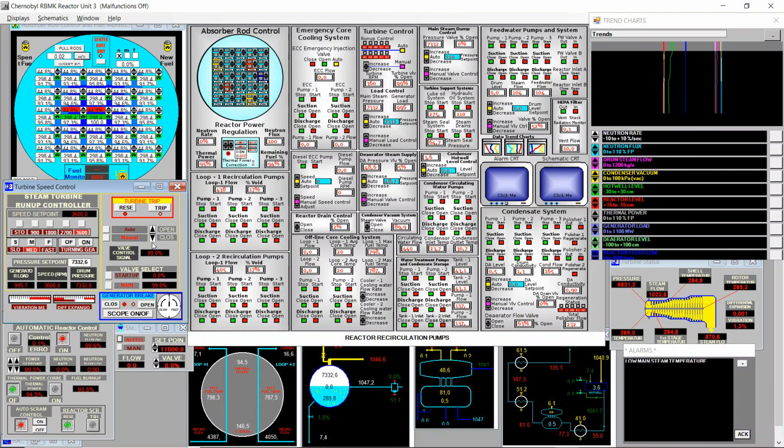996 almost. I will open a bit more. We're at just 5.5% of 100%, and we didn't reach, but I will open a bit more. We're at 100% opening of the main valve, and we're at 1000 megawatts. Now it decreased back to 999 because we're at a really low power, so I will close back a bit the valve to avoid a too low pressure in the drum.